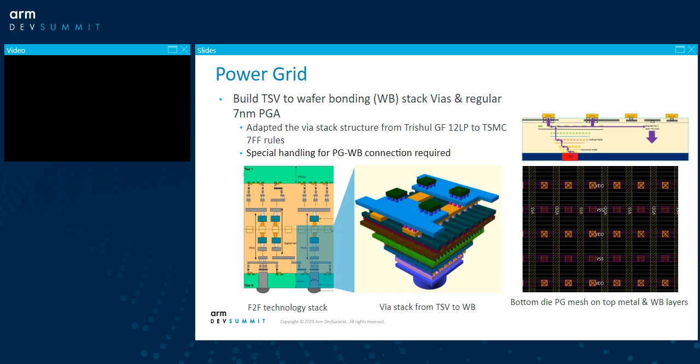So how to minimize IR drop will be a key focus, to make this 3D stacking design feasible from the voltage drop perspective. So that's why we propose to build this so-called stack via, or you can say a waffle via, to minimize the effective resistance to the die interface, as shown. I will talk more about this in the IR analysis section later on.